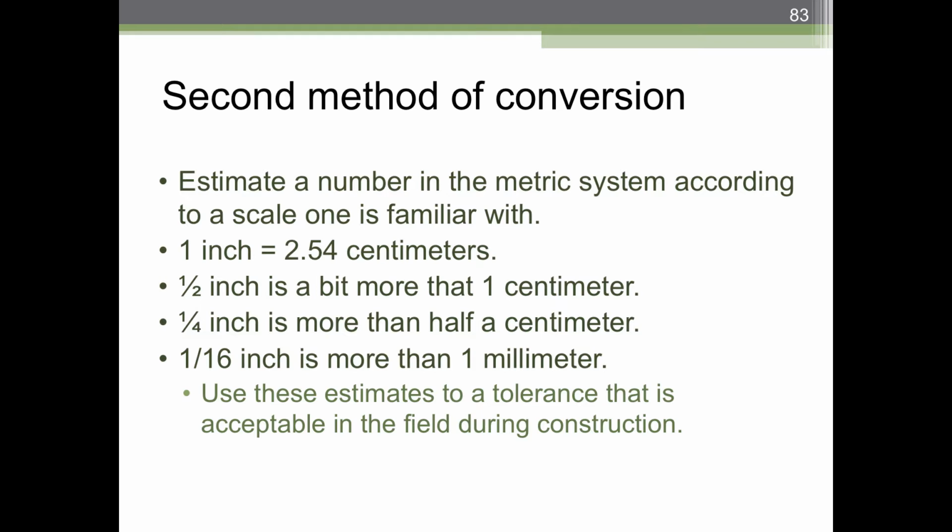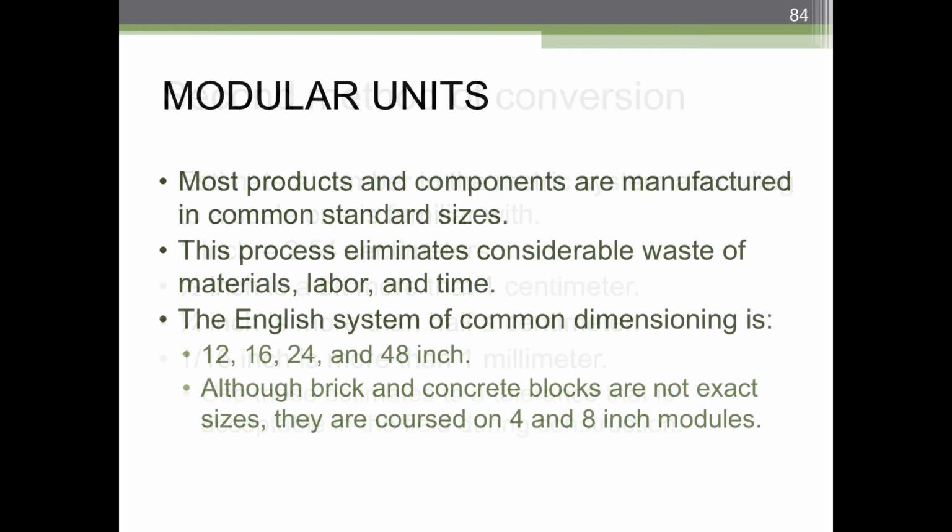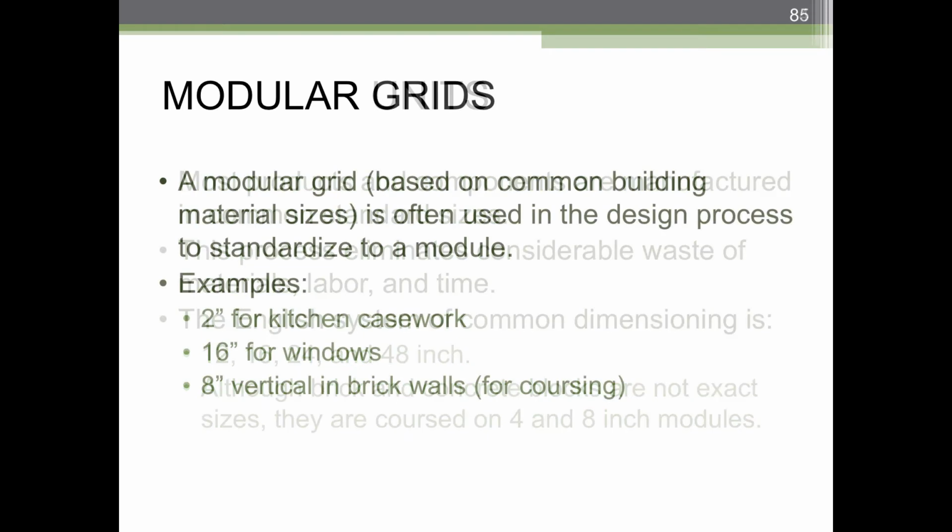Okay. But in the rest of the world, and again, some of you may end up working on projects overseas, you'll need to familiarize yourself with metric. And one big difference, of course, is going to be modular elements. We typically use things like drywall, sheets of drywall, sheets of plywood, any sheet goods, even countertops. They are all common standard sizes. Even brick, which itself is not necessarily a standard size because the grout lines are variable. They're handmade, or at least they typically are handmade, although there are industrialized brick panels, but those are typically exterior. Anyway, but we do know that brick coursing is actually standard. 3 courses is 8 inches for your standard American size brick.